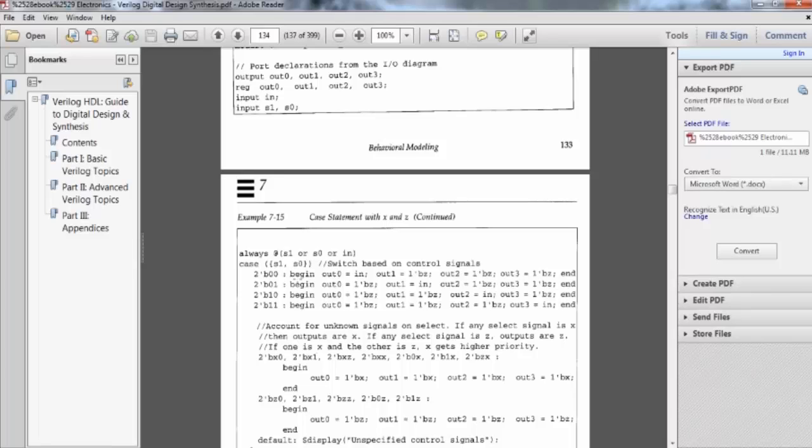Okay, so this is how the case statements are used for writing the code in behavioral languages. And you must have used the begin and end statement also. After always, we should use the begin too, right? Yes, we should use the begin. So I use begin, case, then alternative, then you again use the begin, then after that it will be end, and then another alternative, then begin the output, then after that it will be going to end. So you can use it.